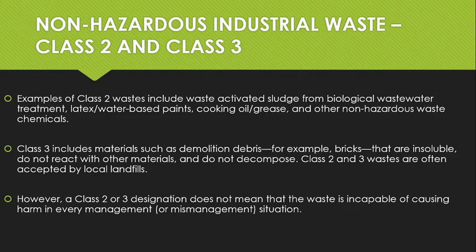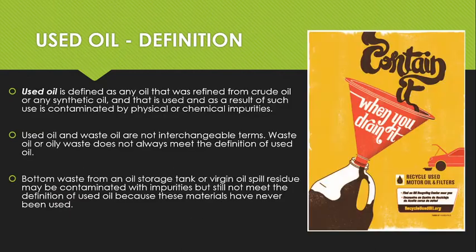Most landfills can take class 2 waste. So we like it when it's class 2 because it's easy disposal. Class 3 wastes are materials like demolition debris, so like bricks, wood, stuff that's insoluble and doesn't react with any other materials and does not decompose. So there you go.